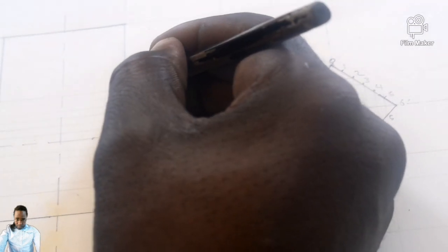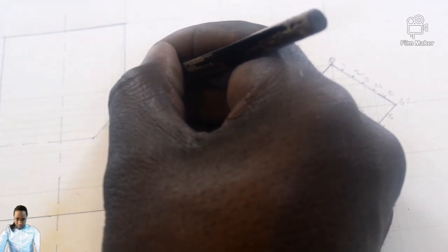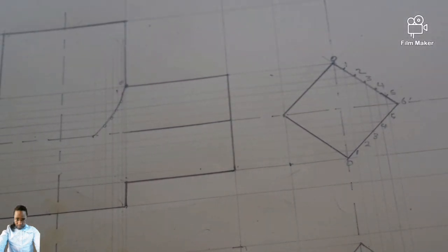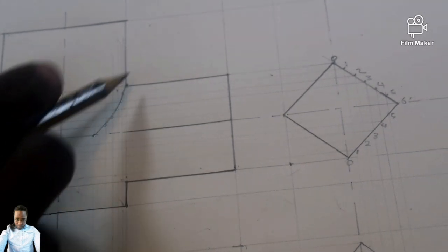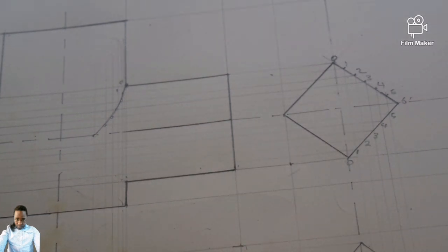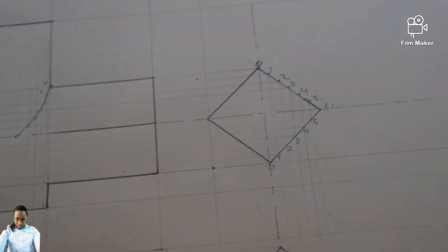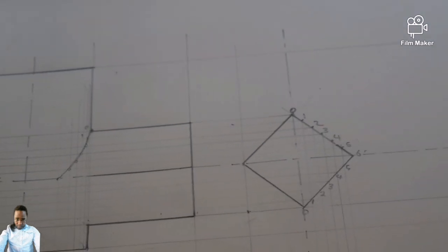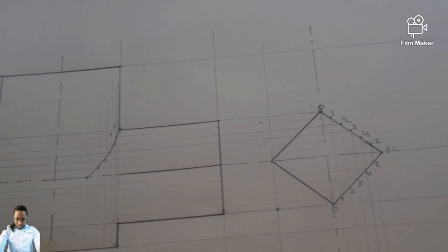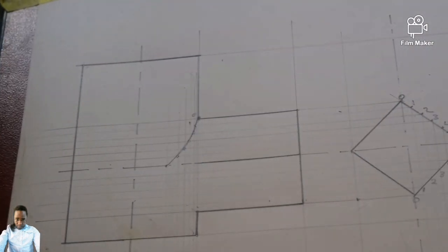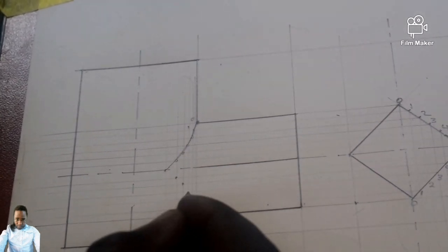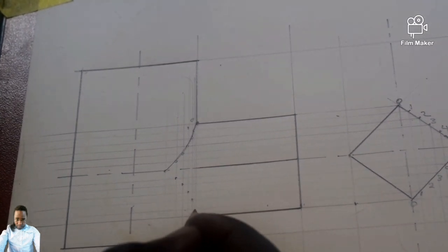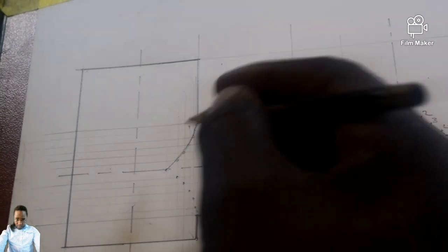So now I can join your points. I can have this arc now. So the other part of it should be the vice versa of this point, the way you've numbered them right from the auxiliary of your front view, like this. So which means again on this side, I've got a point here, a diagonal point there, a point here, and a point there.